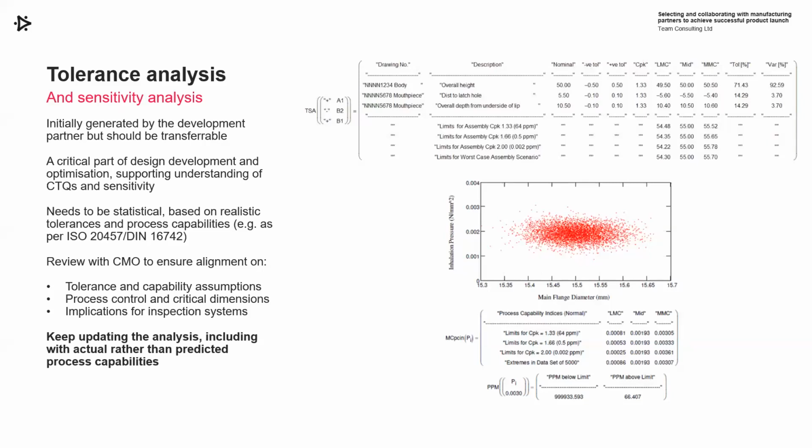Another thing that having a good tolerance analysis supports is reconciliation of parts and acceptance of change late on. If you have tools and during qualification you want to relax a tolerance perhaps or shift a dimension, then having a good robust tolerance analysis helps with that decision-making process.